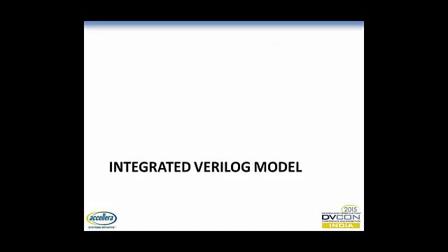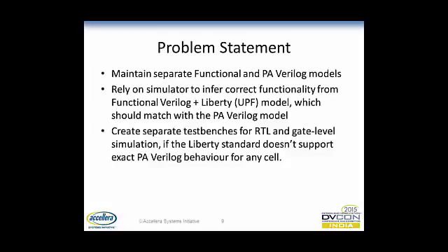Now I'll go into the various issues we face in system level power aware simulation and some of the proposals we have for those issues. The first one is the integrated Verilog model. Right now, as we have seen, a physical IP vendor has to maintain two separate models, functional and power aware Verilog models, and they have to rely on the simulator to infer the correct functionality from functional Verilog plus the Liberty model, and that should match the power-aware Verilog model.